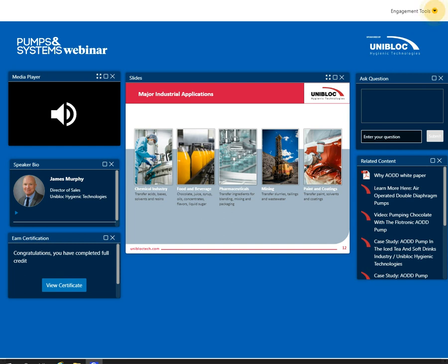Then moving on to mining. Mining is actually where the diaphragm pump was invented for dewatering applications in mines. I think it was in the late 40s, early 50s. There was a need in mines for dewatering, and they didn't want an electric motor or electrically driven pump. So that's when they came up with the idea of using an AODD pump for dewatering. And being an air-powered pump, in this case aluminum or stainless steel, they are inherently safe for an explosion type application.